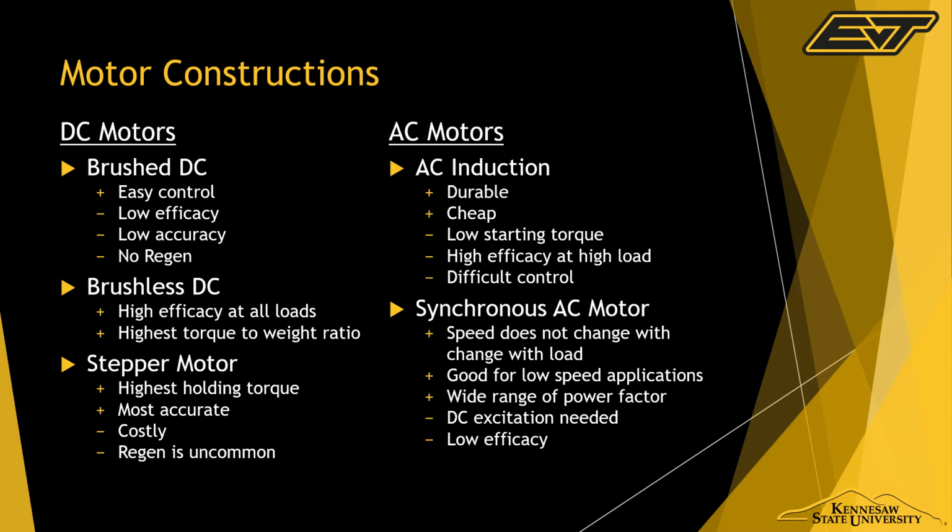Now on to AC motors. Basically, there's two kinds of AC motors: synchronous and asynchronous. Asynchronous are the induction motors, and the reason why they're called asynchronous is because the rotor actually moves slower than the magnetic field.